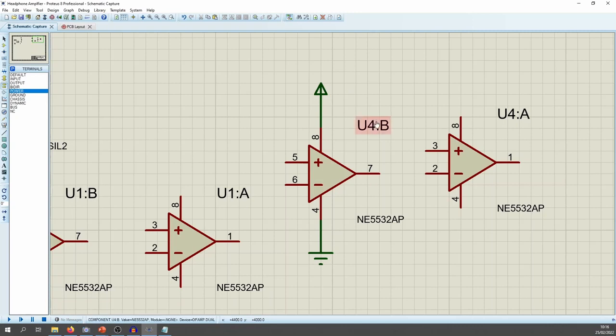So basically in Proteus, I don't know if this is going to answer your question or not, but once you've put a power net onto this pin, you don't need to do anything with this. Oh, I know, but say you just didn't want to put 8 and 4 on there because you know they're used by both. Oh, you mean just separate out 8 and 4 to a different chunk, right? Okay.